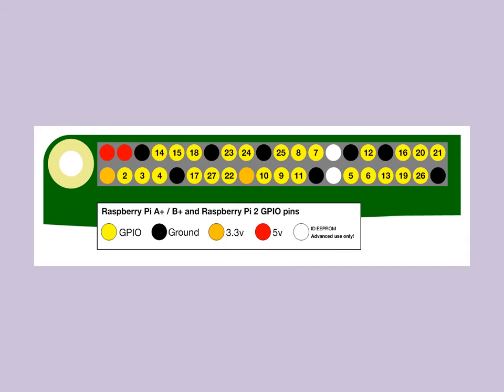The Raspberry Pi 2 Model B has many general-purpose input-output pins that we can use to create our alarm system. This figure illustrates a map of these pins and their corresponding GPIO pin numbers. We can see that there are a couple of 5V and 3.3V leads, multiple connections to ground, and plenty of GPIO pins that we can use for the logic and control of our system. Each GPIO can be set to either receive an input signal or send an output signal, depending on our needs.